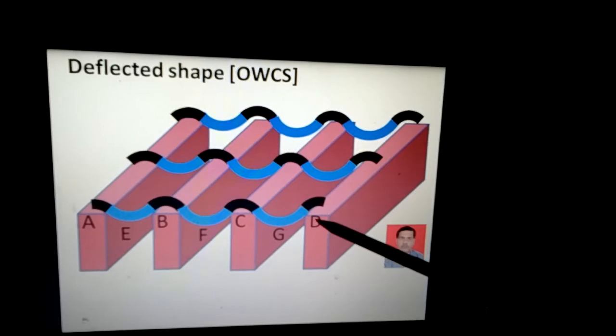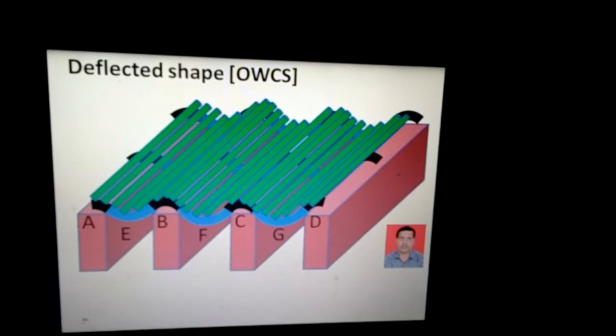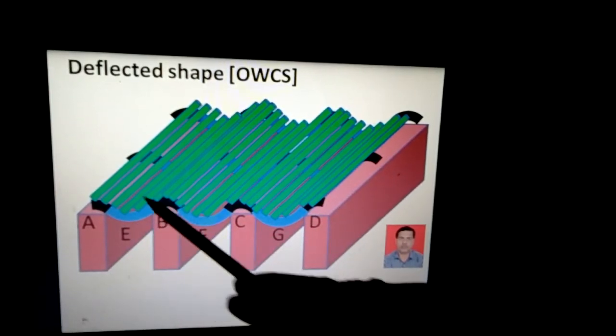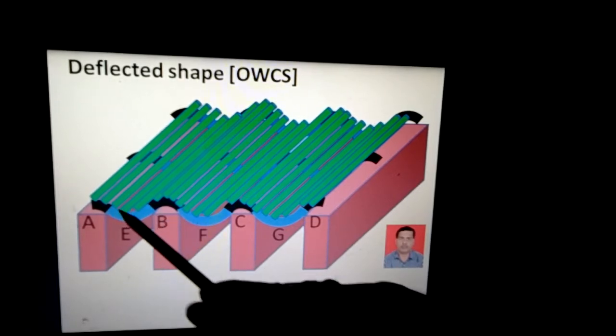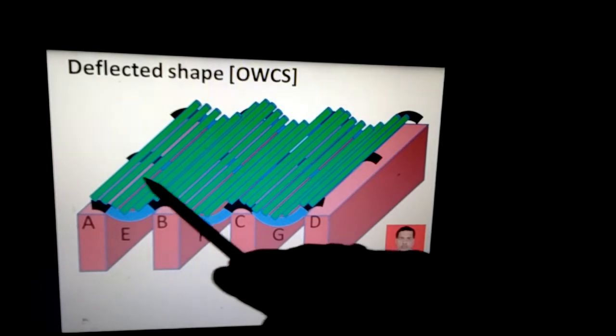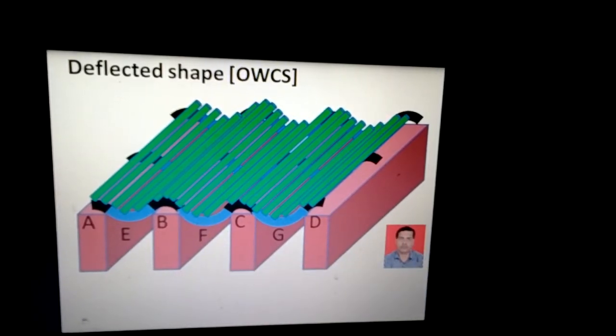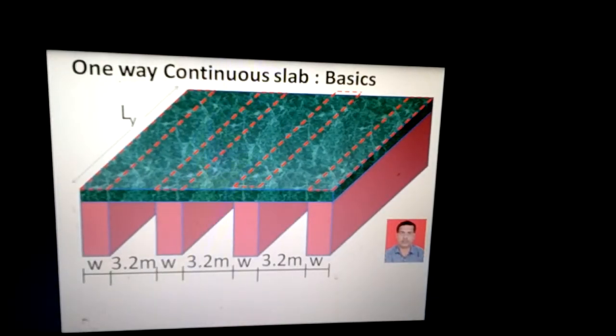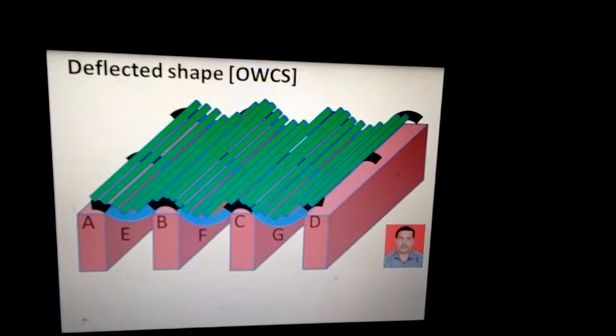And if we have an imaginary slab in this case, then it would look like a slab covered with folded surfaces. You can see this span has a downward folding, and near the supports it has an upward folding. So the flat slab, which was initially in the first image, is going to have a deflected pattern, and this becomes like this. So the one-way continuous slab is going to deflect continuously, and each span is affected under the influence of the load and its bending moment.